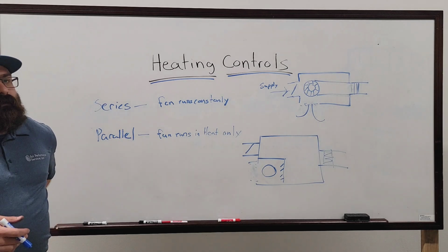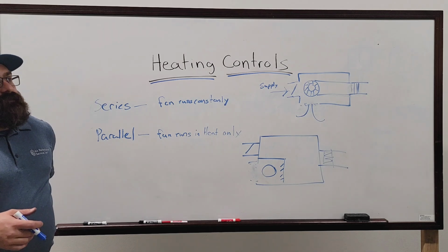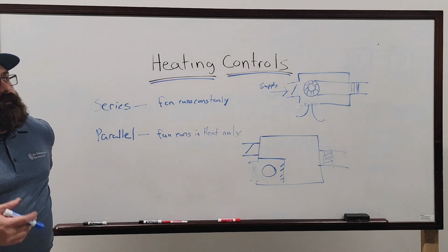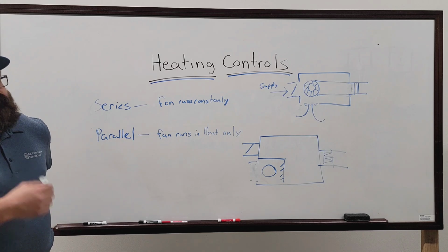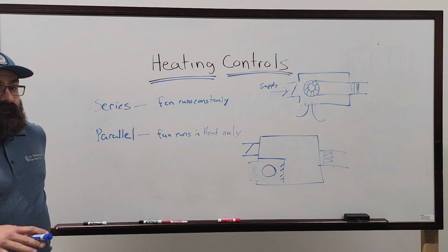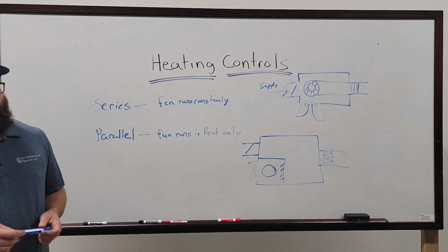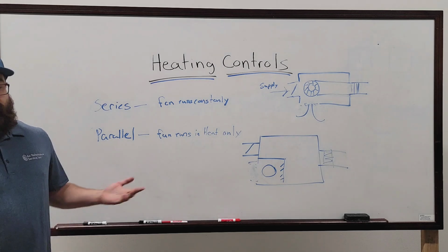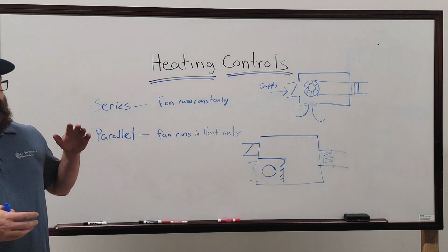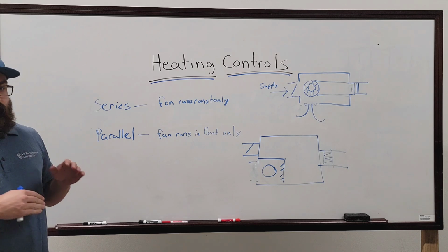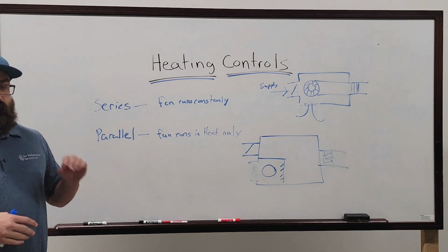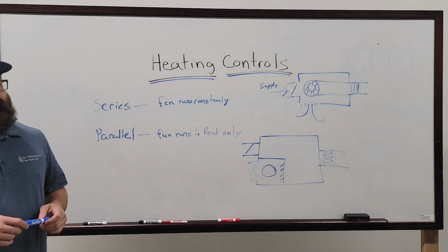Very few systems will have the ability to run the heater without the fan on in a fan powered box. There are VAVs with electric reheat or hot water reheat that it doesn't matter. They will be programmed to maintain a minimum CFM through the box, which is enough to trigger that airflow switch.